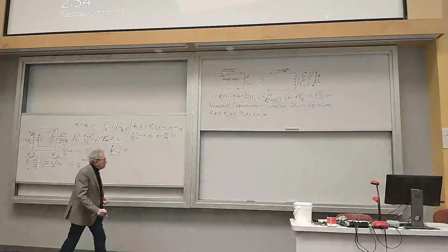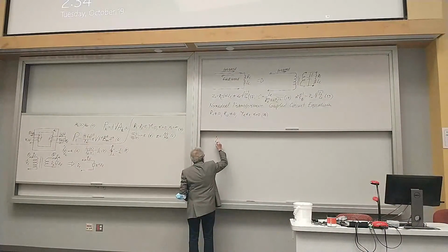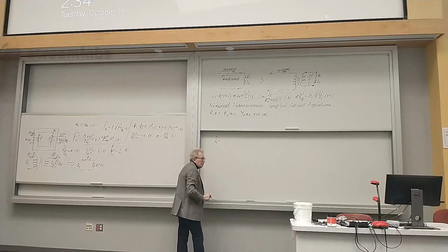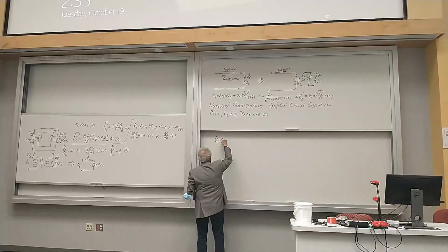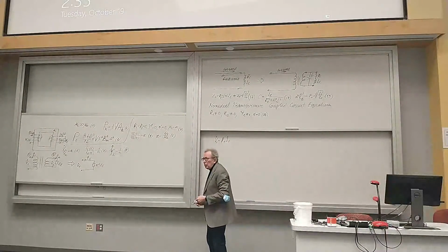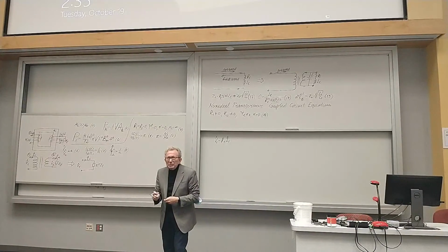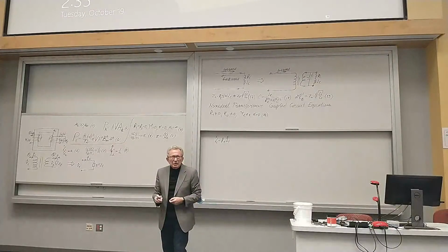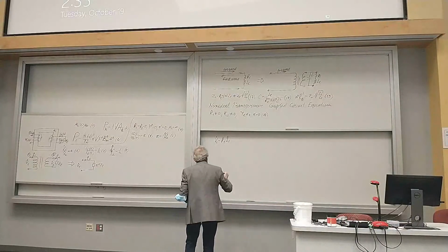If I write Kirchhoff's voltage law for the primary winding, then the input voltage V sub 1 will be equal to the voltage drop across the resistor, due to the resistance of the winding. Then there is the voltage induced in the primary winding by the magnetic flux created by the current through the primary winding, due to the inductance of the primary winding.